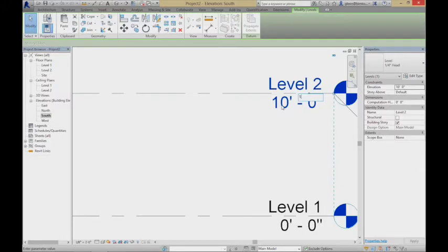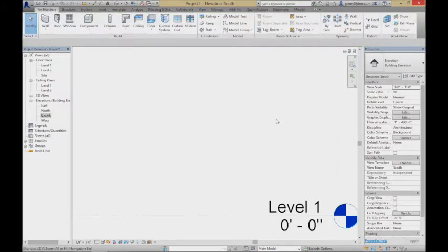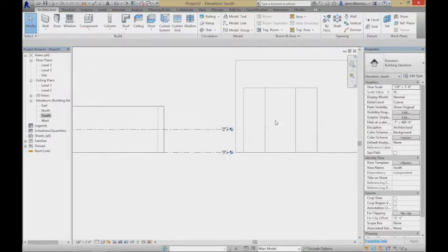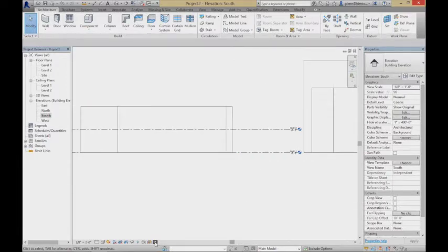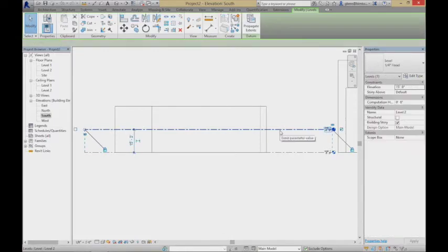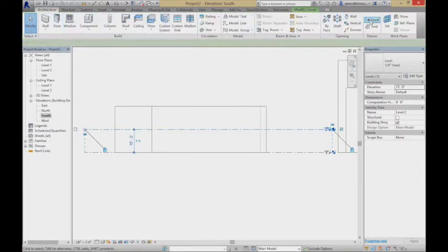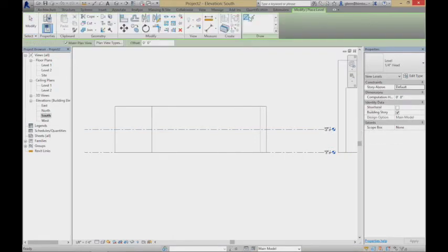So I'll make that floor height 15. Again, I'm doing that because in buildings of the scale of the Y2E2 building, there actually are fairly tall floor heights to accommodate all the mechanicals. I'll choose that level and I'll put that in here and I'll offset again 15 feet.